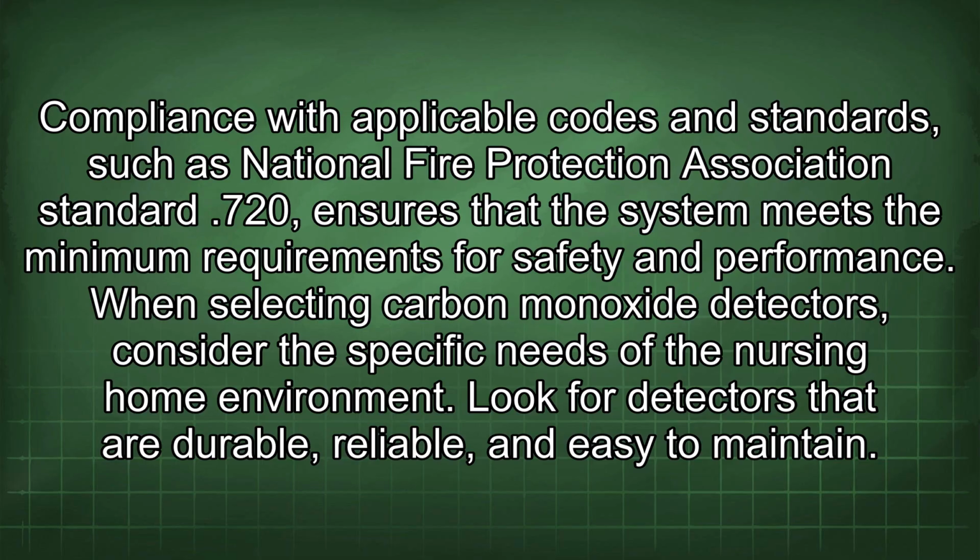Compliance with applicable codes and standards, such as National Fire Protection Association Standard 720, ensures that the system meets the minimum requirements for safety and performance. When selecting carbon monoxide detectors, consider the specific needs of the nursing home environment. Look for detectors that are durable, reliable, and easy to maintain.